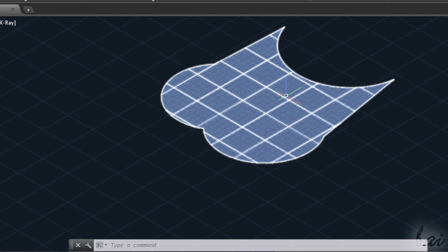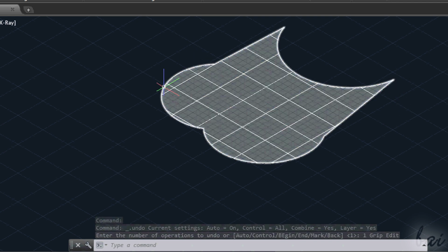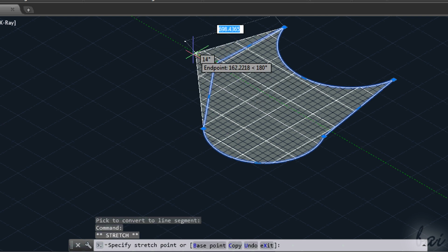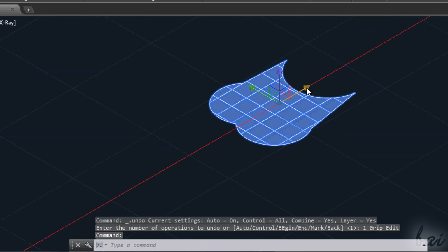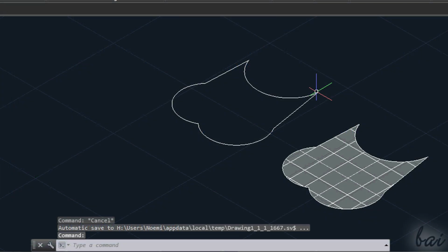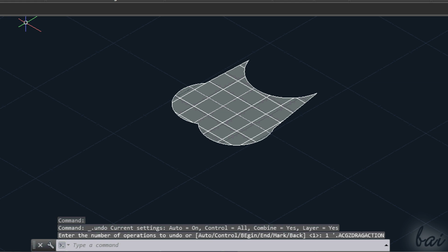Mind that the old polyline contour does still exist after creating the surface. This contour and surface are associated. If the polyline is edited, the surface follows. This strong link is lost whenever you move the surface. That becomes independent. As you can see, even if you use a 2D wireframe view, the surface is indicated through a checked object,